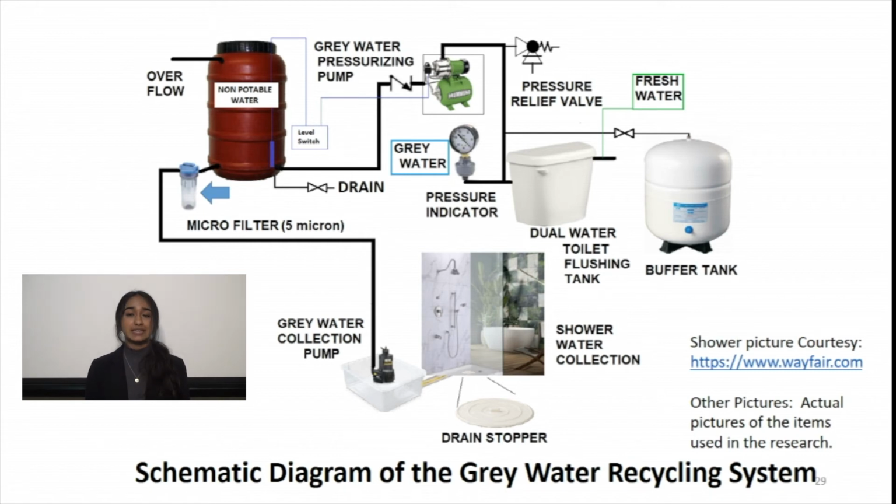pump to the tank. I bought a gently used barrel that was originally used for the international shipping of pickles, which was fitted with overflow lines with multiple drain holes. I then installed the tank in my bathroom on a table and equipped the tank with a drain line and an overflow line. I used a pump that has an automatic on-off feature based on the discharge pressure. I also installed a level sensor to sense the water in the tank to disable and enable the pump.